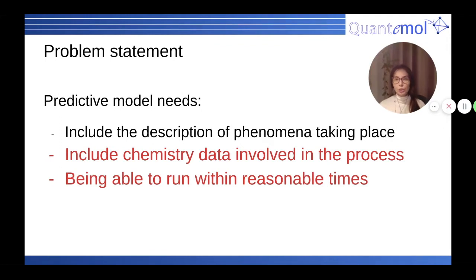connected. Including all possible chemistry would be ideal. However, in many cases, it will hinder or make it completely impossible to run simulations with all possible species and all possible reactions. So naturally, people try to remove some reactions or species which seem to be less important, for example, removing them based on small concentration and so on. On the other hand, you run a risk of removing some key species, which will make your simulation results completely invalid.